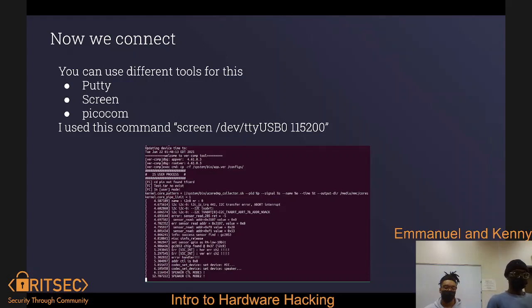Can I talk a little bit? Personally, I suspect it's a multitude of things. I think either Emmanuel didn't solder it in there correctly, so it was like a cold solder joint, and it just didn't make complete contact. Or these devices come from China, and I'm not knocking China or anything. However, these are just known to be dead on arrival on occasion. These are mass produced. Or three, the camera's dead, like a trace probably got scratched, something like that. I don't know. It's alive.